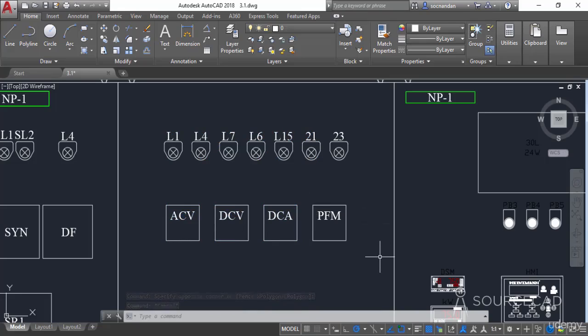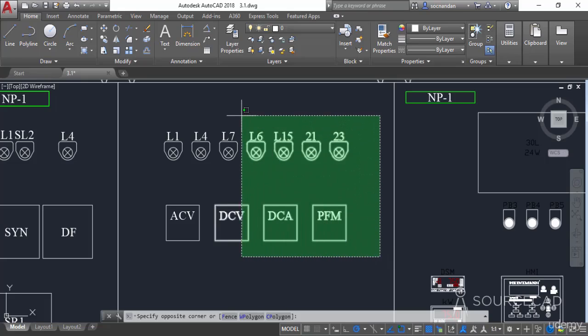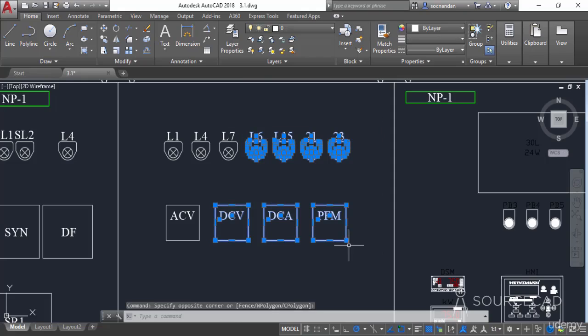Now let's repeat the process with another window. I'll click on the right side of the drawing area and move my cursor towards the left, and now we have this dashed window. In this case, everything completely inside this window is selected, but also the objects which are touching this window are selected. This rectangle and the text are included in the selection set, although they are partially inside and partially outside, because they are touching the window. So this is the second way of selecting objects.